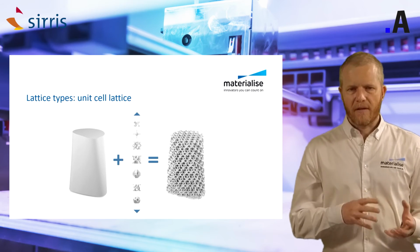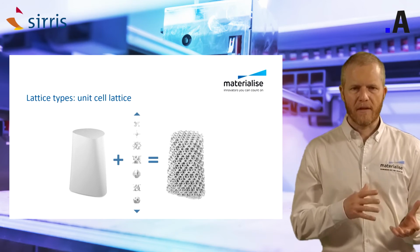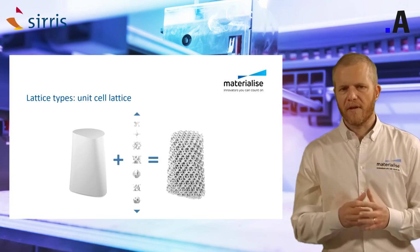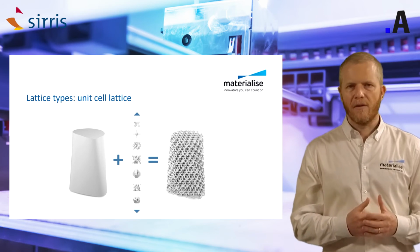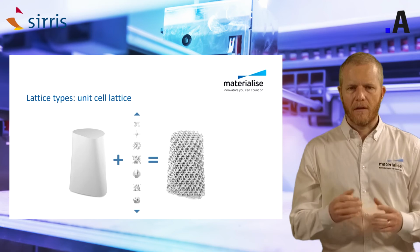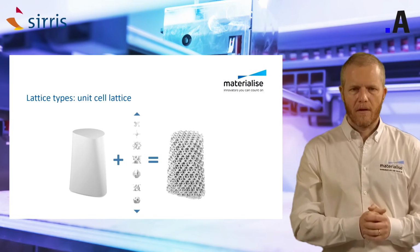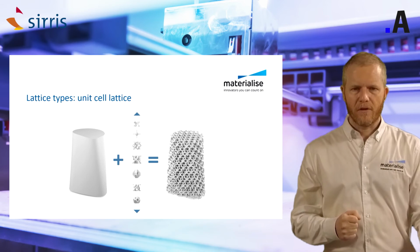So, the different kinds of lattice that are available in Chromatic. We have the unit cell lattice, where you specify the volume that you want to fill with the lattice structure. You specify the unit cell that you want to use. We have a library of unit cells available in Chromatic, and you are also free to create your own. It's quite easy to do in the software, so you have a lot of freedom in that regard. Here you see how it would look: the volume, the unit cell, and the volume which has been replaced by the lattice structure.